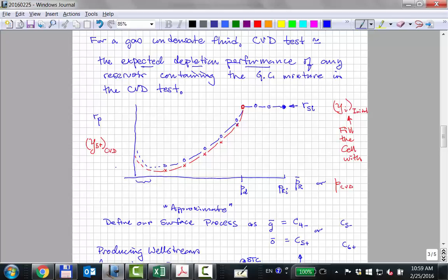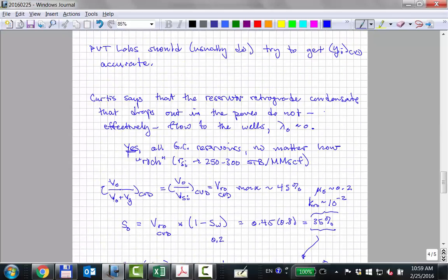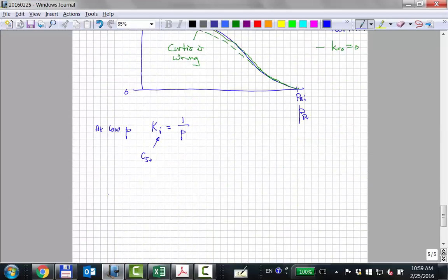As you get to low pressures, the K values of all these heavy components go inversely proportional with pressure, so the components want to be more and more in the gas. So this is the revaporization. You can call it that, but it's just the K values. Revaporization is just a word. It's the K values getting higher and higher for all of the heavy components.